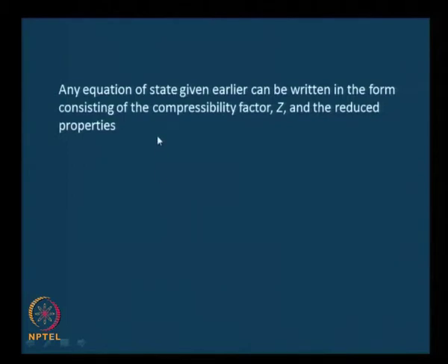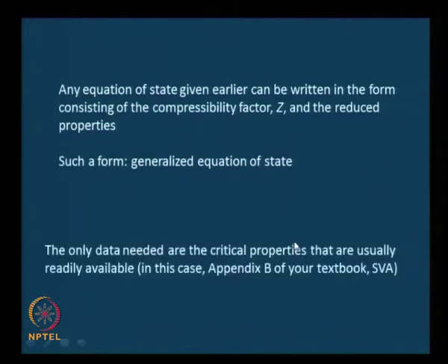Not just that, any equation of state can be written in terms of the reduced form or the generalized form if it is written in terms of the compressibility factor and reduced properties. And to re-emphasize, the only data that is needed when we use the generalized equation of state are the critical properties that are readily available, for example in the appendix of your textbook.